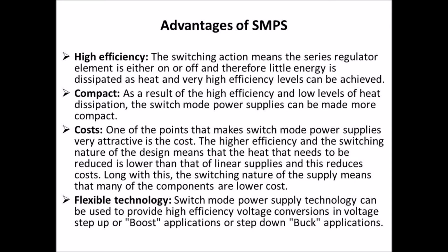Next, we can discuss the advantages of SMPS. First one, high efficiency. The switching action means the series regulator element is either on or off, and therefore little energy is dissipated as heat and very high efficiency levels can be achieved. Second one, compact. As a result of the high efficiency and low levels of heat dissipation, the switch mode power supplies can be made more compact.